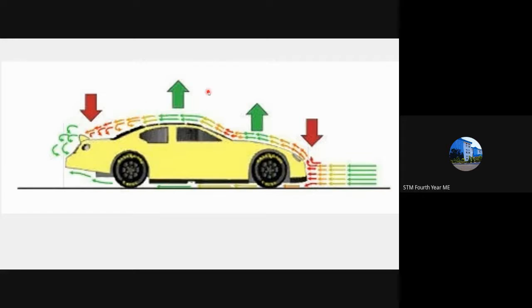But the vehicle lift at the center portion of the vehicle, the green area that is shown, always occurs as lift. There is no possibility of making a negative lift here. But if you achieve negative lift at this point and this point, the vehicle always stays on the ground. So that is our aim. We can't provide it here, while we can provide it here.